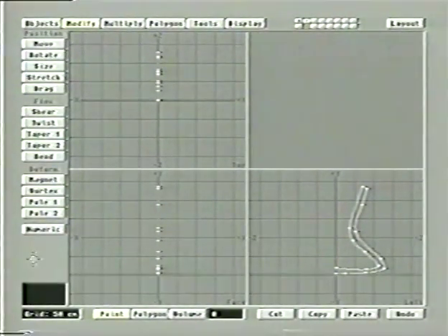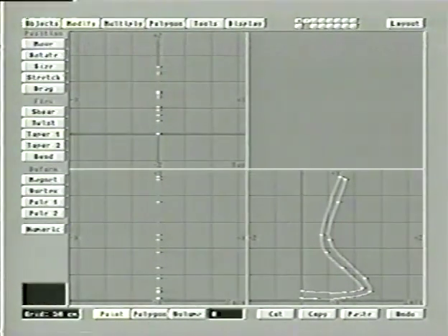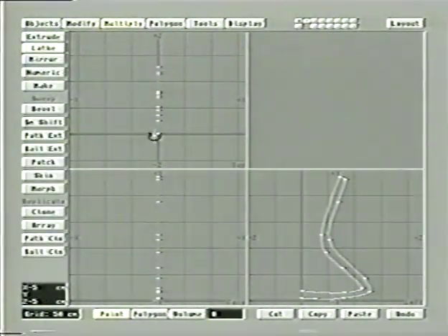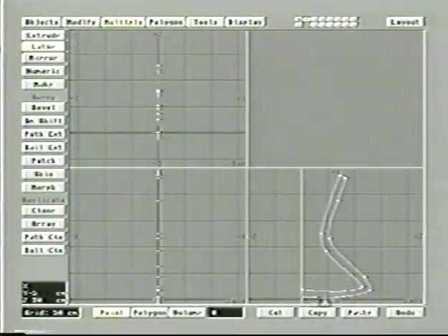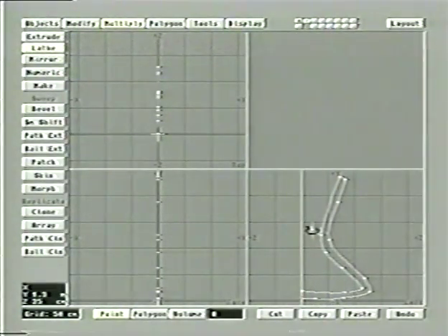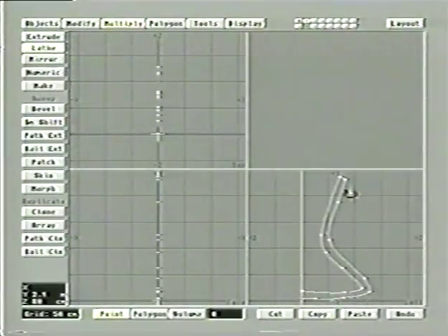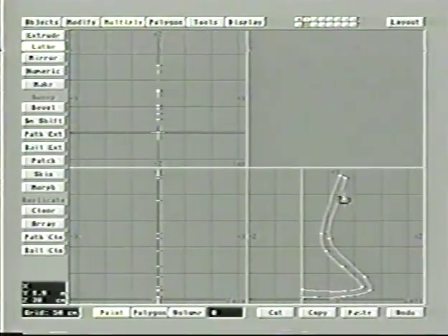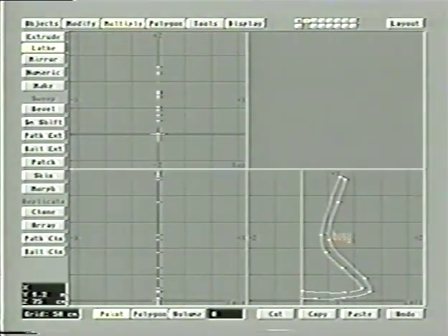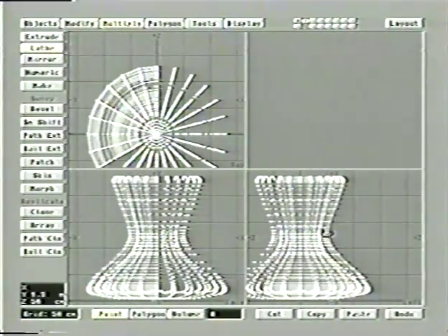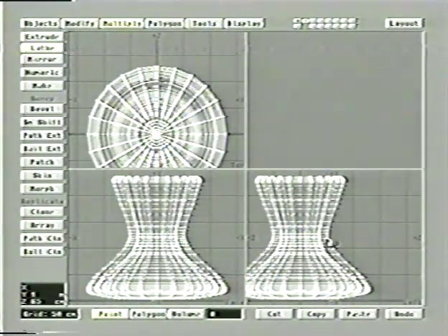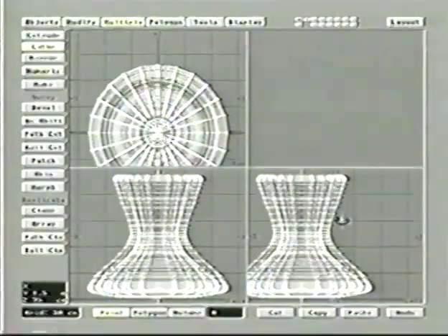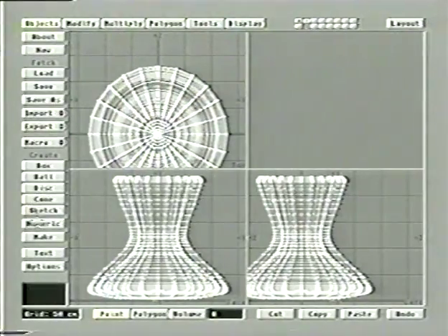And again, normally this is a part where you'd spend a bit of time. What I want you to call attention to here is the fact that since these are curves, when it lathes it and turns it into polygons, obviously it's going to need more points along there. And watch what happens right along here. Like you notice there's 1 point here, 1 point there. But when we lathe it, there's suddenly a whole mess of points along here, a whole bunch of them. Now, how does it determine how many points to put along there? Well, that's determined from your Objects, Options menu.